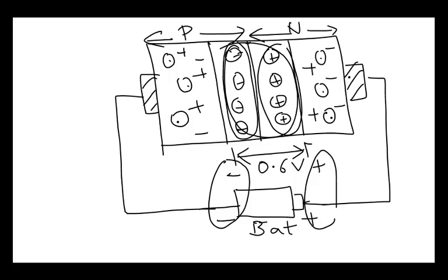can no longer stay there and start hitting atoms with huge forces. This causes electrons from the atoms to be knocked off from their position, thus creating new electron-hole pairs. So as the battery voltage increases, these ions start moving this side and these ions start moving this side, and they start hitting the atoms here, and they knock off the electrons from these atoms, creating new electron-hole pairs.